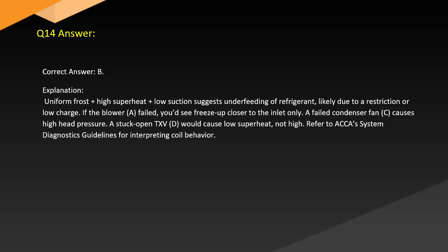Answer. Correct answer B. Explanation. Uniform frost plus high superheat plus low suction suggests underfeeding of refrigerant, likely due to a restriction or low charge.